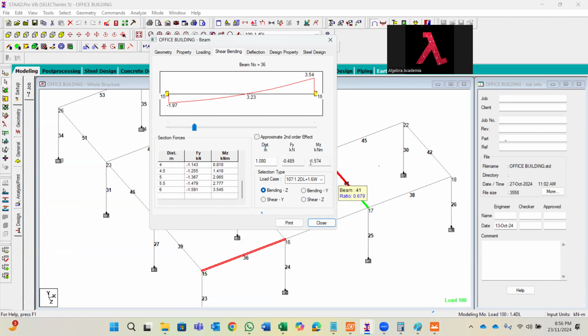The advantage you get is, in order to extend by 1 meter of beam by welding from the factory, you reduce the moment by 30% further. By this 30% reduction, you can optimize your plate thickness and the bolt diameter as well. Are you trying to understand, trying to get my point? Because instead of giving the splice connection at 50 cm, I move another 50 cm, which is 1 meter, to reduce my moment by 20 to 30 percent.